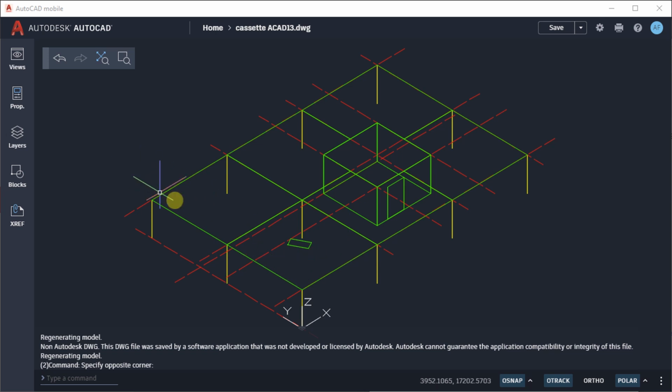Now I could have chosen to do the entire floor as one single area. Personally, I don't like that. I just want to have each of my slab bays individually defined. And the reason I'm making an issue of the types of line is that these can all be interpreted by GSA in different ways as we import it, and we'll see that when I open GSA.